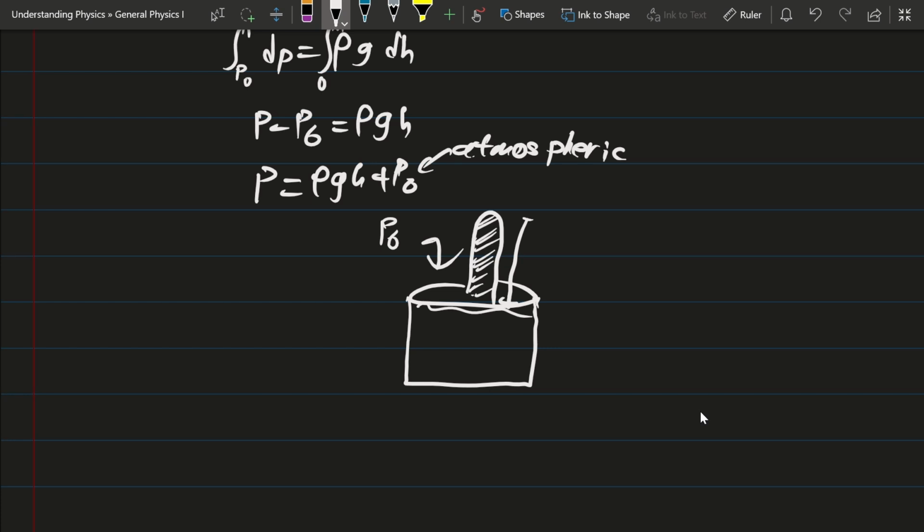And why is that? Because you can just fill the entire test tube with mercury first and then flip it over and make sure that there's no gas leaking inside towards the pillar of mercury. So you would get an accurate reading in terms of the height of the mercury. So if you actually try to solve this, this is basically P0 equals rho gh.